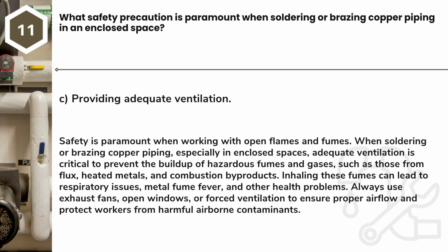Safety is paramount when working with open flames and fumes. When soldering or brazing copper piping, especially in enclosed spaces, adequate ventilation is critical to prevent the buildup of hazardous fumes and gases, such as those from flux, heated metals, and combustion byproducts. Inhaling these fumes can lead to respiratory issues, metal fume fever, and other health problems. Always use exhaust fans, open windows, or forced ventilation to ensure proper airflow and protect workers from harmful airborne contaminants.